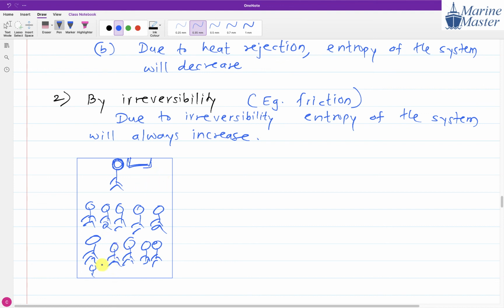So in peak summer, what is going to happen? The temperature will increase inside. Suppose in peak summer in central India or North India, anywhere in India except a few places, the surrounding temperature is higher and the room temperature is lower. So the surrounding heat is going to enter the room. There is a heat addition. Q addition is there.